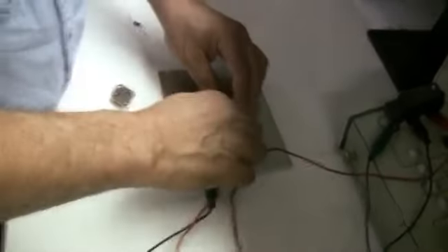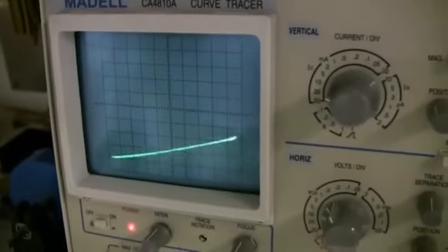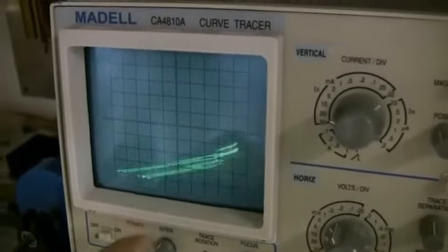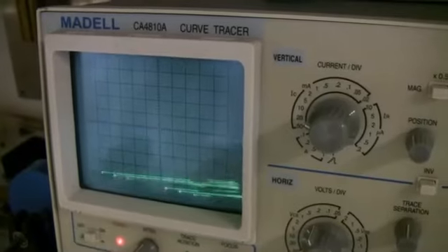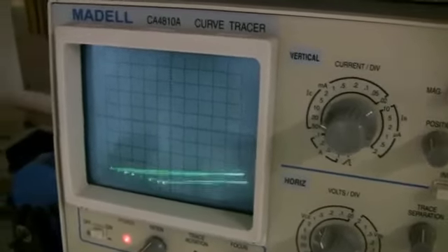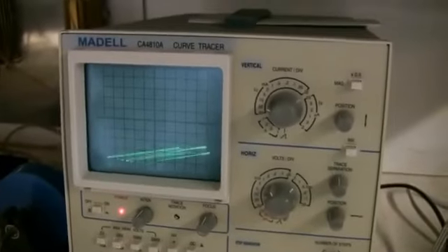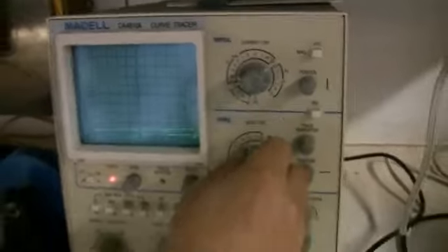we use the aluminum for the emitter, and then we'll just use this for the collector. We use a piece of wire for the base. So you notice right away we have a junction. And see, when we get this where we want it, then we get a transistor. More in the high frequency end here. See?